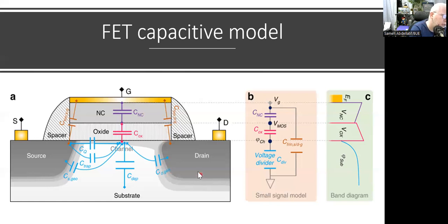For example, if you are working below in the substrate region, that means you don't have this channel. So any capacitance related to the channel will not appear. For example, if we have a drain voltage equal to 0 and a source voltage equal to 0, then you will have these p-n junctions under thermodynamic equilibrium with a constant depletion region. But if you force any of these two to be in reverse bias, for example, then you should expect a larger depletion region.